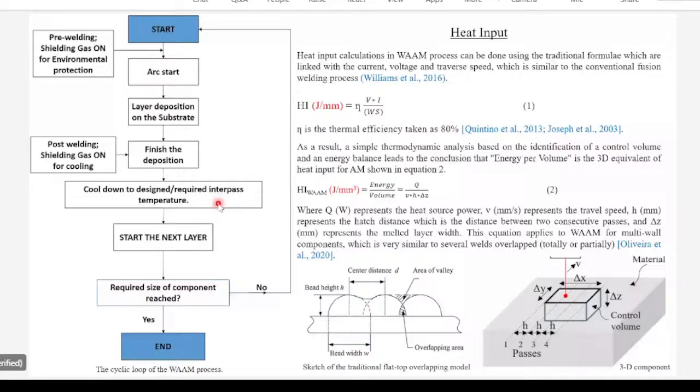As we are doing this, we are attaining a constant thermal gradient, and what we can achieve is a good homogeneous material, a 3D component we can make. We can quantify that also with tensile specimens. We can take out 0 degree, 45 degree, and 90 degree specimens, and we can test that material and check whether the anisotropy is high or low. So that we have to check.